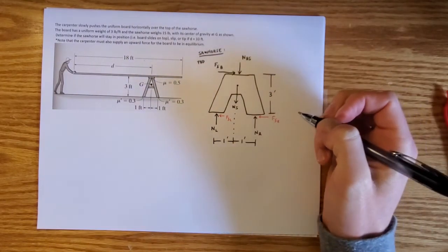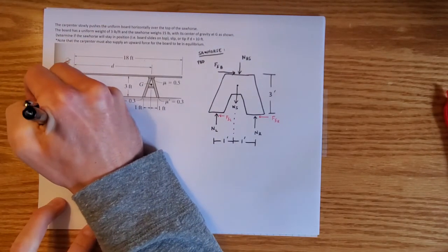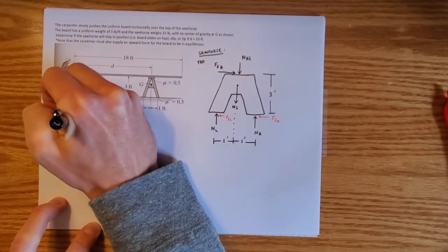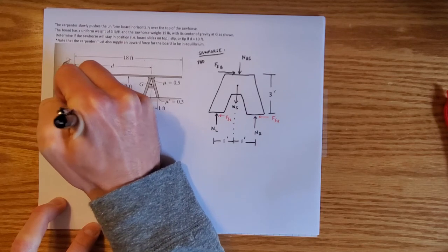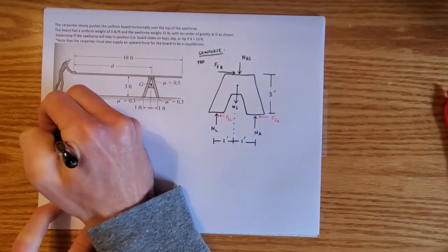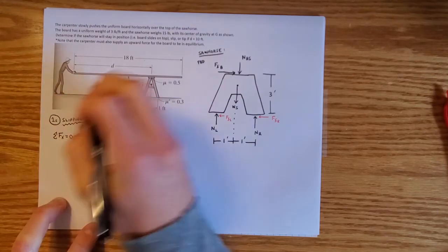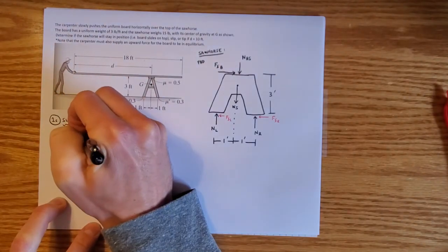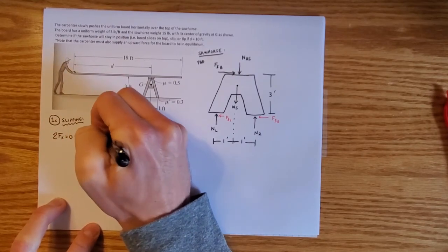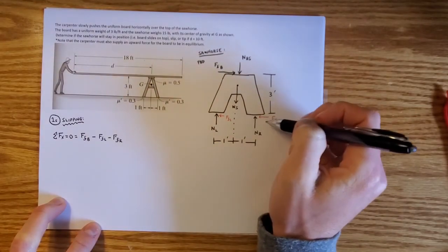Okay, that's it. Now for our sawhorse, there are 2 conditions we need to check. So condition 1S for the sawhorse, and we actually luck out, the S is going to be slipping. Now how do we do this? Effectively, we write a sum of the forces in the X equation. So the sum of the forces in the X is equal to 0, which is equal to FFB, the force of friction from the beam, which we already technically have, minus the force of friction on the left leg, minus the force of friction on the right leg. So that's the 3 things that we have.